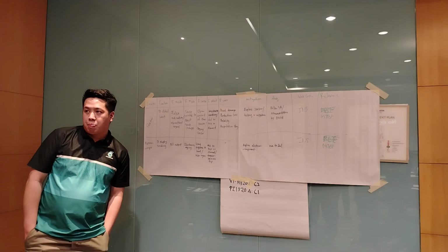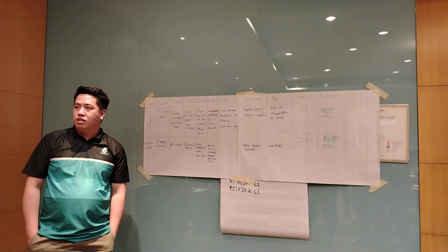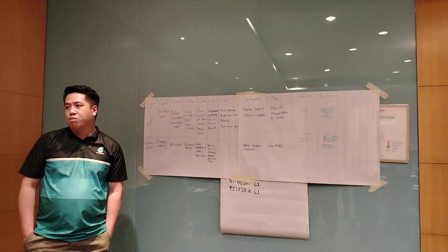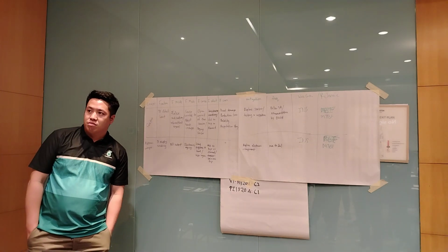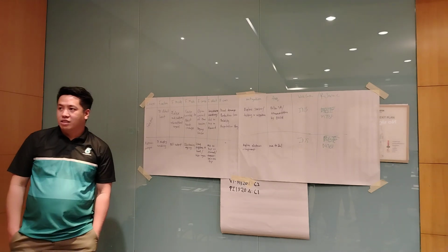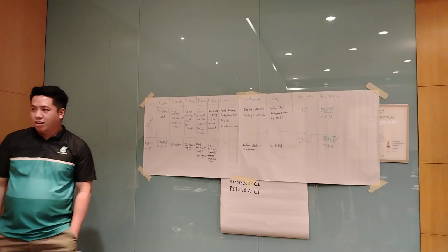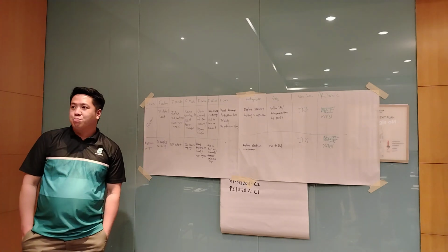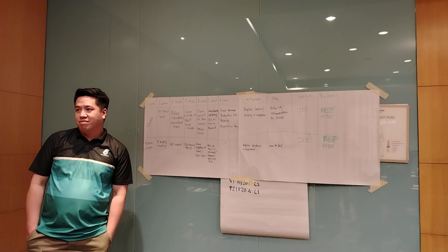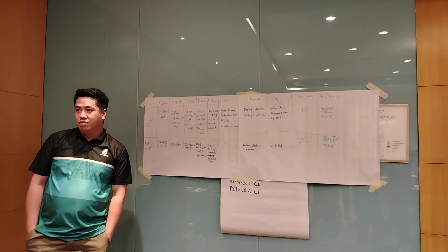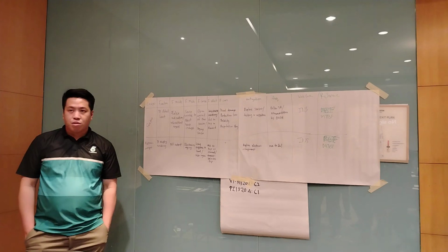So when do you want to replace it? Usually every TA we replace the heat detector, UV detector and so on. So the TA is every 6 years? 3 years. So you have an extra 3 years even though your aging sensor can last 25 years. Yes, it's better we replace than have any accident happen. Cheaper. So you can see what kind of strategy they are going for? Time based.